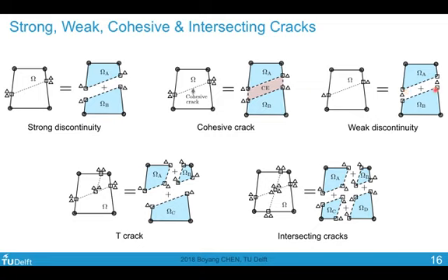So you have shared degrees of freedom here, but a discontinuous strength field because you have a different Young's modulus. So this is entirely possible and is very straightforward. However, this is not so straightforward in the case of phantom node or XFEM. And also you can make use of,